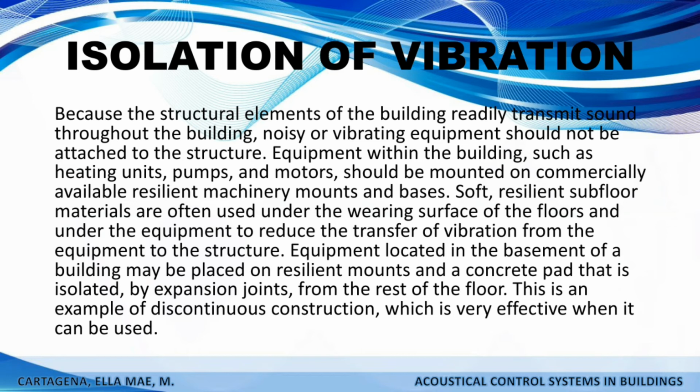Equipment located in the basement of a building may be placed on resilient mounts and a concrete pad that is isolated by expansion joints from the rest of the floor. This is an example of discontinuous construction, which is very effective when it can be used.